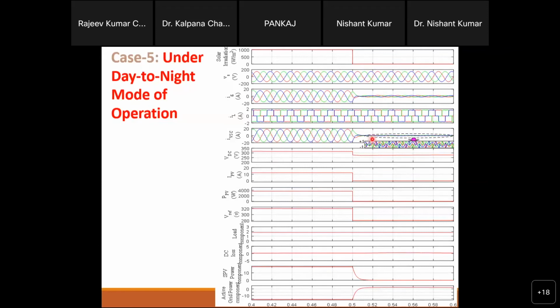Because here our VSC, voltage source converter, is acting as a D-STATCOM and generating the nonlinear current demand. All the nonlinear current demand of the load is coming from the VSC side, so that only active power will come from the grid, and then this grid current is pure sinusoidal, right? You can see this one, and this magnitude is less. Why? Because this magnitude is only according to the requirement of the load current.